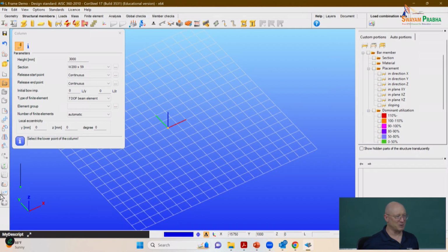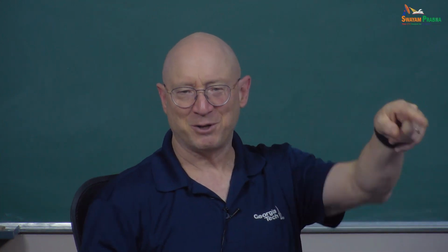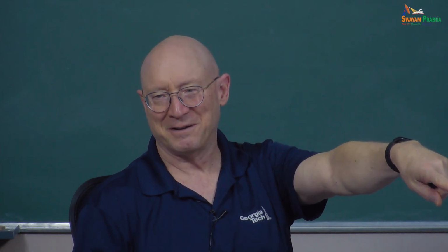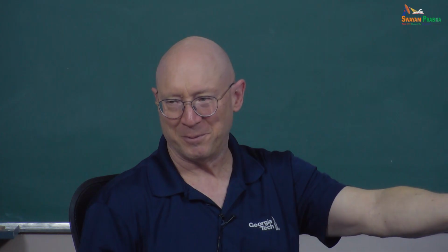So I basically say, I have a girder that goes 200 feet. I've got various members connecting into that girder. I draw the whole girder, and I draw these other members. Consteel recognizes these come into the same point and puts a node there, so I never have to explicitly define that node.